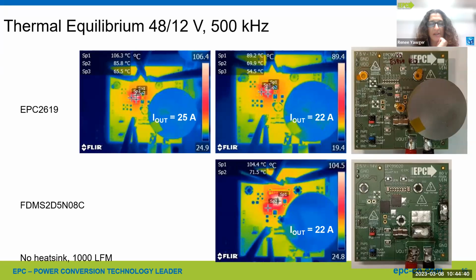Next is, can we consider the GaN FET as small enough to be a lumped component within the operation frequency range for optimization? I would say yes. For example, in our SPICE models, we don't provide any parasitic inductances because they're so small that typically the main contribution to parasitic inductance is actually from the layout. So the component itself, I would say yes, but the layout usually is not.